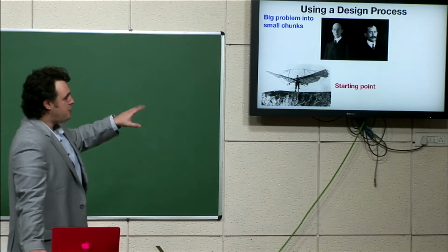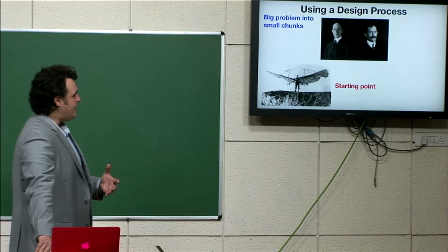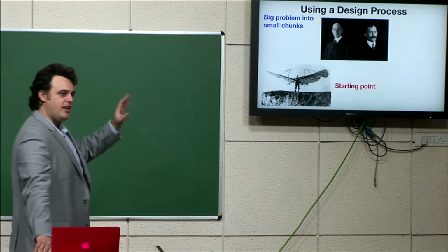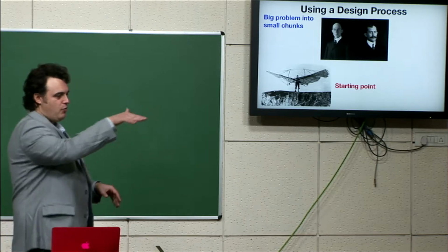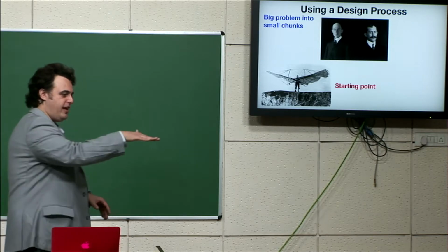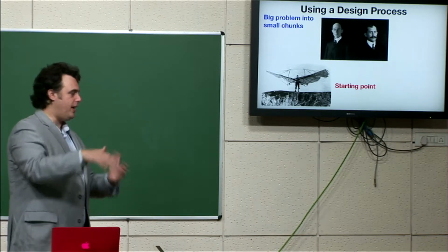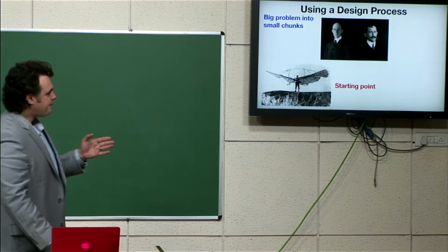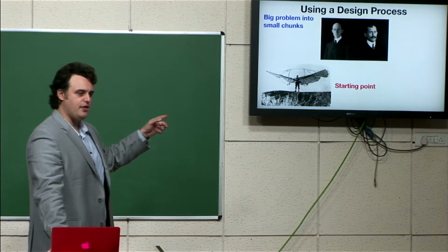And so the Wright brothers, being good academics, they read about the background of the work, and they said, all right, we want to make a glider based on his lift to drag tables of wing shapes, right? So for a given wing shape, you could know as it's moving through the air, given the velocity, how much lift it'll make and how much drag it'll experience, right? So they made a glider, and they realized it didn't work anywhere close to what was predicted by Lilienthal's tables.